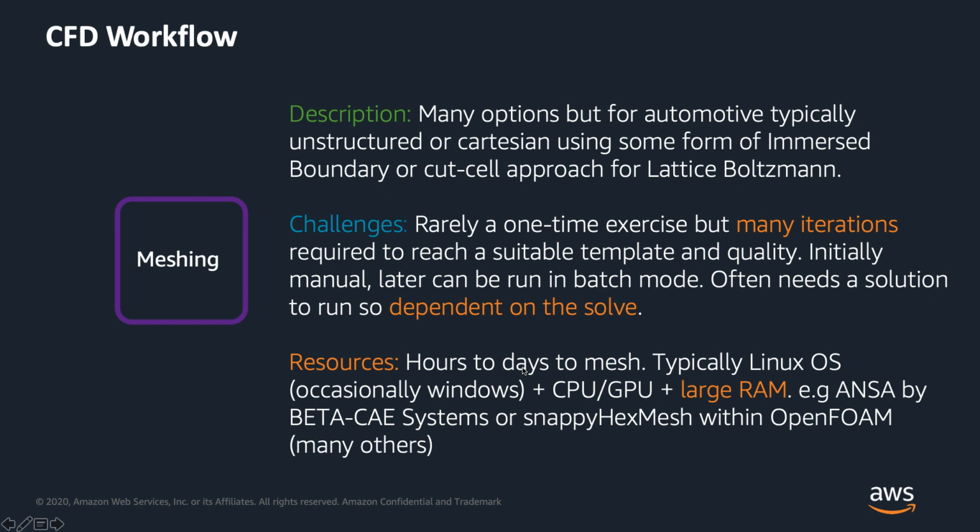The resources is hours to days to mesh, depending on the size of the case and the complexity. It is typically Linux, although maybe for smaller things and for personal preference, it could be Windows. It's the CPU that's driving this, but a GPU to maybe visualize these large grids. Large RAM, you could easily get beyond 64, 128, more than 200 or 300 gigabytes of RAM. Starts to put a pressure on really the sort of desktop that you might do this on.